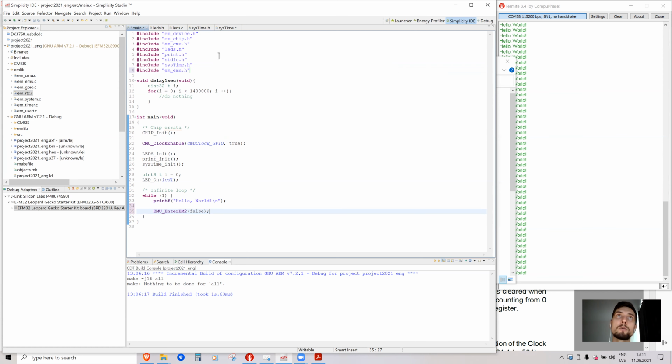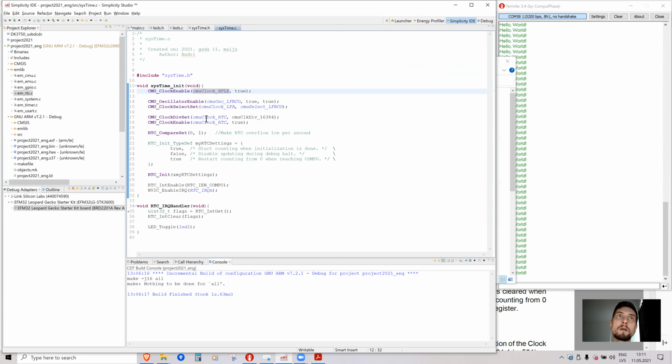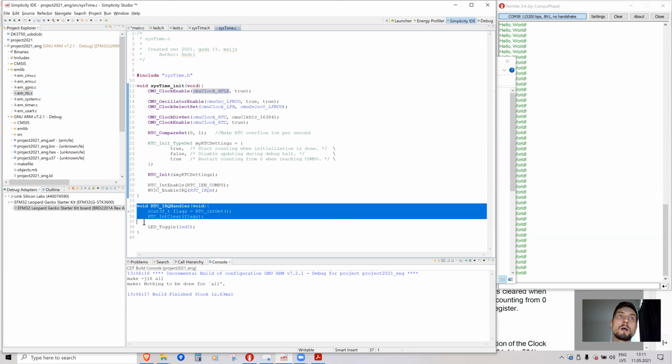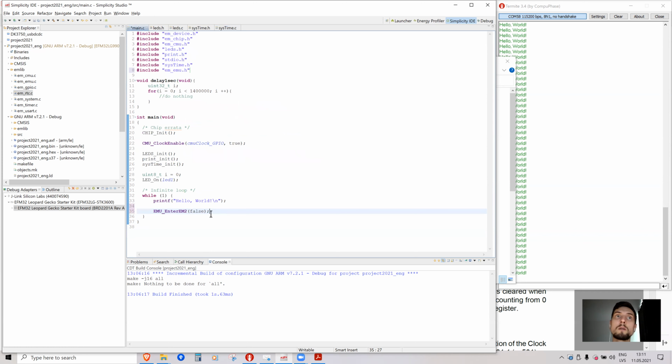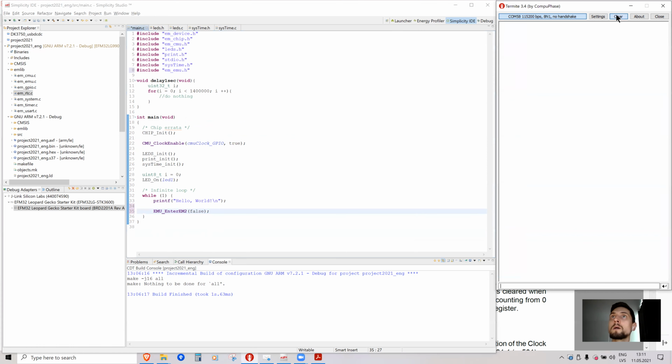But in the background, the real-time clock is running from a different clock. And when this 1 second passes, it wakes the CPU up to execute the IRQ handler, this interrupt. And after the interrupt, the CPU stays on, so it resumes the action and goes into this loop back and types hello world again and goes to sleep again. So this is how it works.